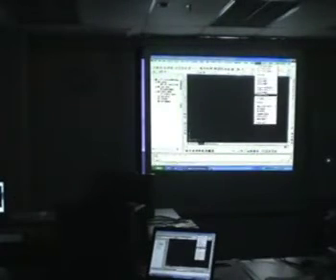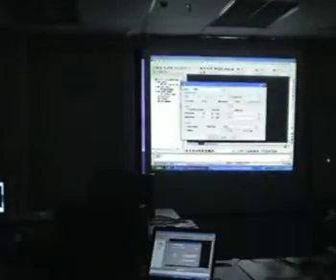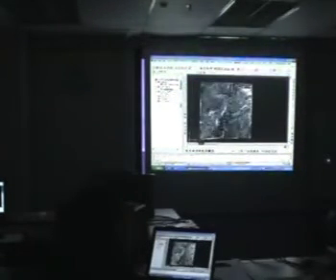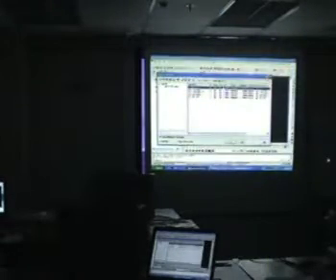Okay, I'm going to create contours. You can see the values have been inserted for me automatically as well. Elevation range from this level to this level automatically for me. You can set intervals at minor and major, minor only, or major only. I'm just going to click OK. So yes, you can see the contours have also been automatically created for me. Again, these have also been created on their own layers.